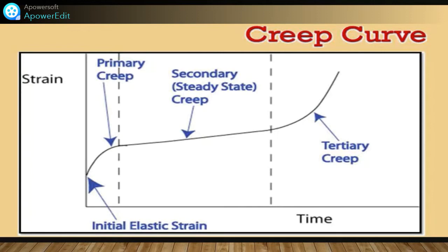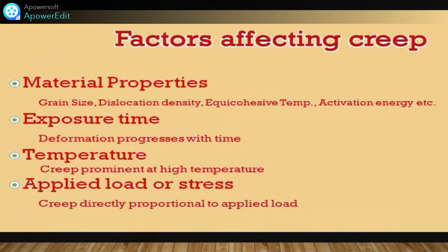This stage is most understood. The characterized creep strain rate typically refers to the constant slope in the secondary stage. The stress dependence of this rate depends on various creep analyses. In tertiary creep, which is not of much importance as far as practical applications are concerned, the strain rate increases exponentially with stress because of necking phenomena.